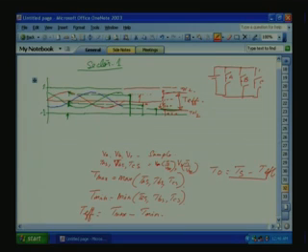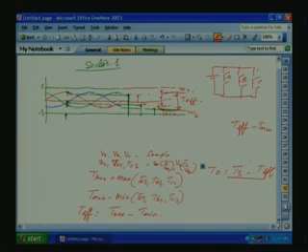So, how do you do it? First, find out the T effective, and we also know the T minimum. T effective minus T minimum will always be negative. Ts minus T effective minus T minimum will shift the whole thing to the positive side. Then again you add T0 by 2. So, the offset to be added, so that everything goes to the positive side, is T offset equal to T0 by 2 minus T minimum.